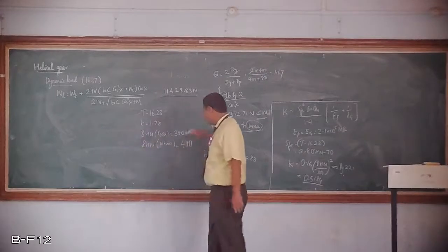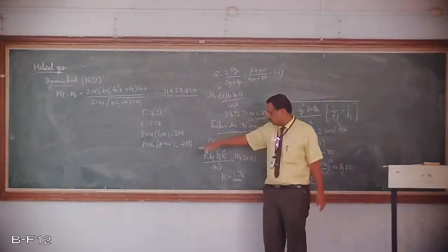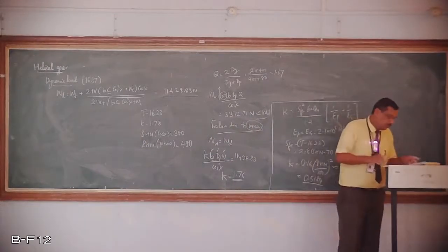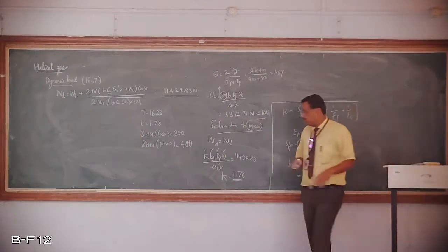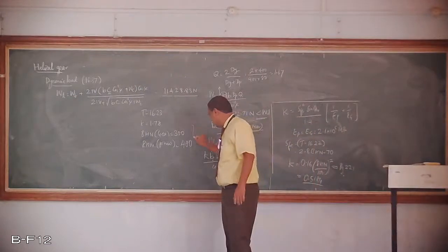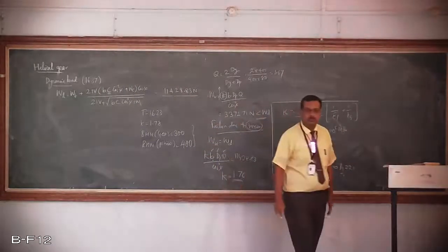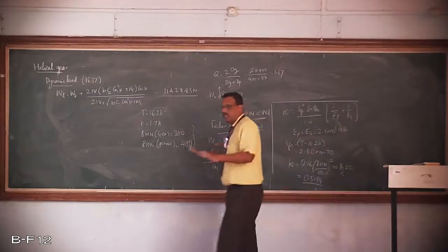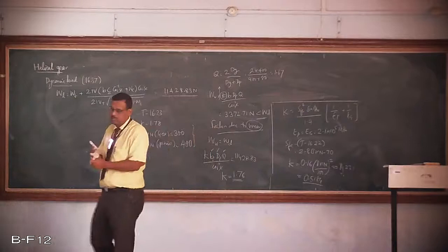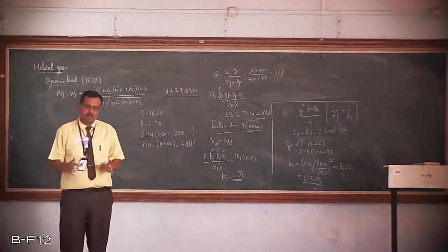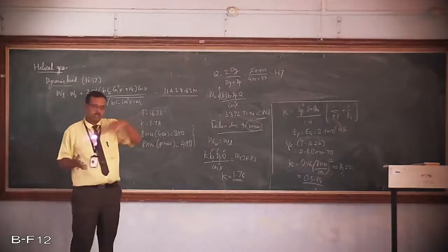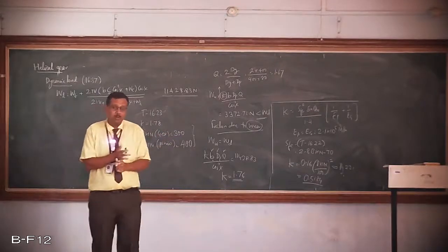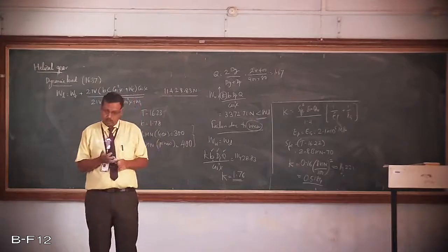Therefore, if the gear is having 180 BHN and the pinion about 250, whatever we have estimated from the properties given, it will not withstand, it is going to wear out. Therefore, at least the gear and the pinion have to be of this hardness. So now we have completed the design of the gear, taking into account the static load. With the static load, we have calculated the dimensions. Once we calculate the dimensions, we have to check whether they will be safe in the dynamic load. Therefore, we calculated the dynamic load using the Buckingham equation.